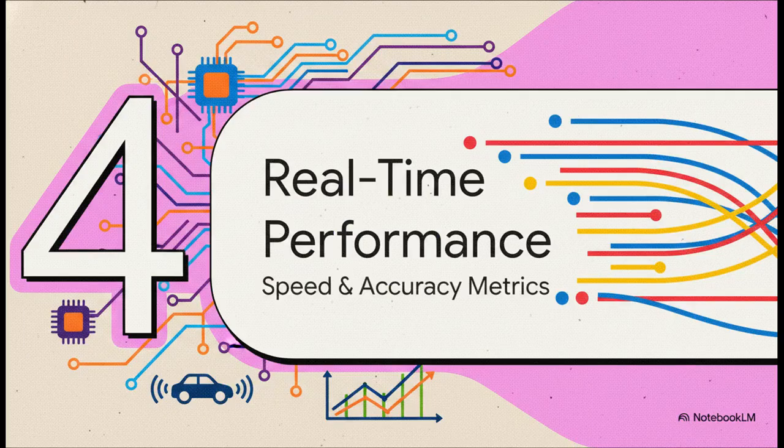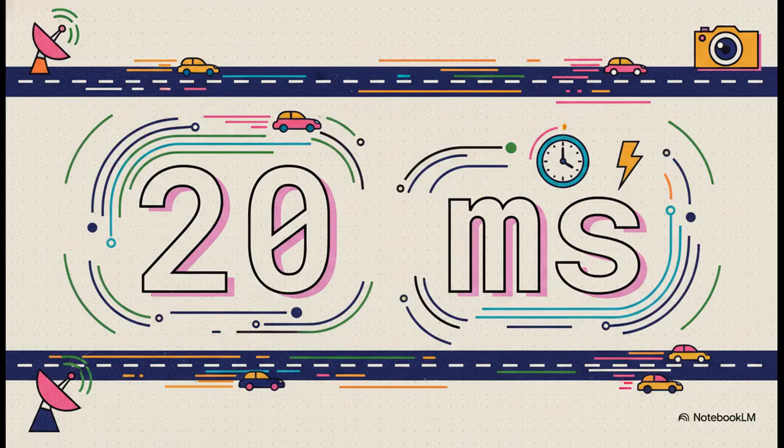Finally, Section 4, Real-Time Autonomous Performance. Let's look at the actual numbers to see if this MATLAB Simulink pipeline actually holds up in practice. 20 milliseconds. That is the blazing fast average inference time per frame for this entire setup. And why does that matter? Well, for smooth, real-time autonomous driving, you generally need to be running at 30 frames per second. That gives you a strict maximum budget of 33 milliseconds per frame to make a life-or-death decision.